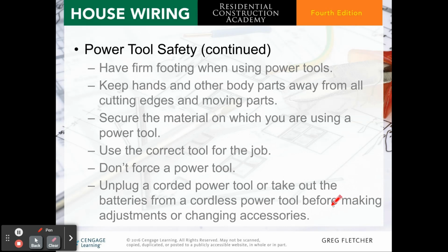Have firm footing when using power tools. Keep hands and other body parts away from all cutting edges and moving parts. Secure the material on which you are using a power tool. Use the correct tool for the correct job. Don't force a power tool. Let it do its job. Unplug a corded power tool or take out the batteries from a cordless power tool before making adjustments or changing accessories.